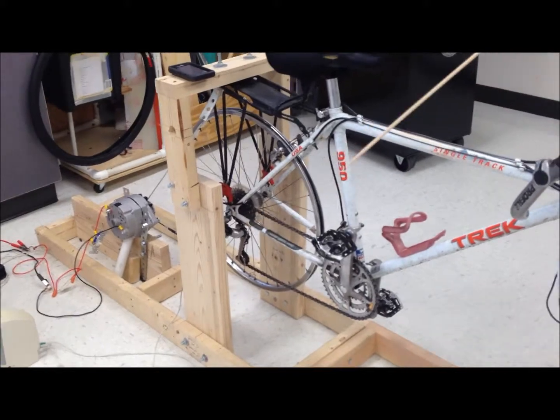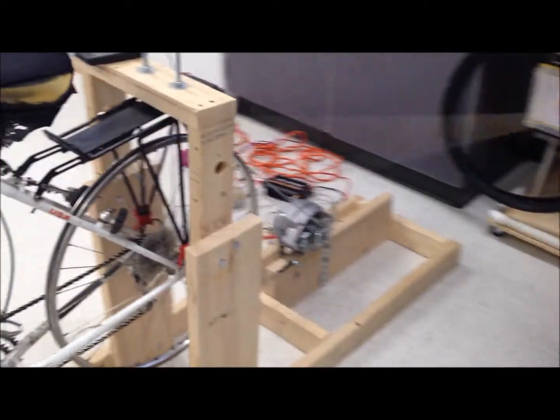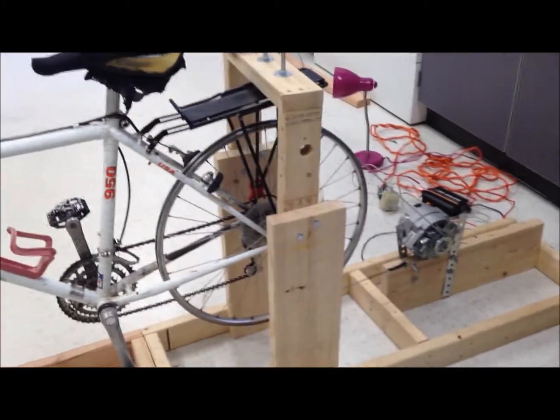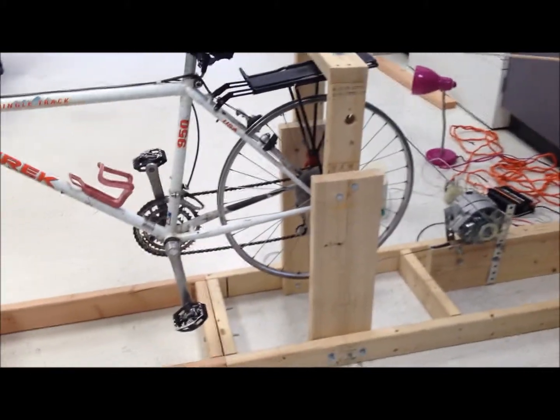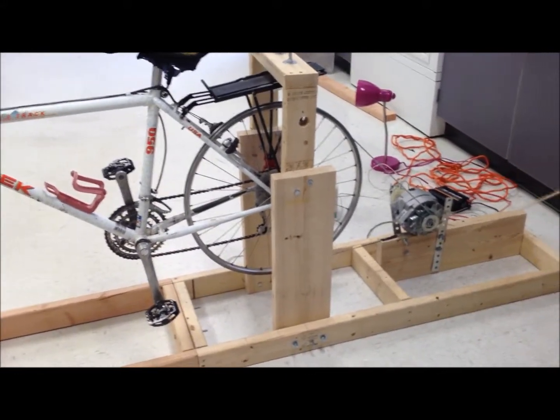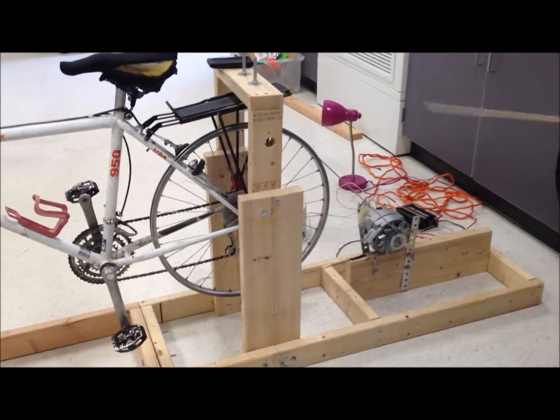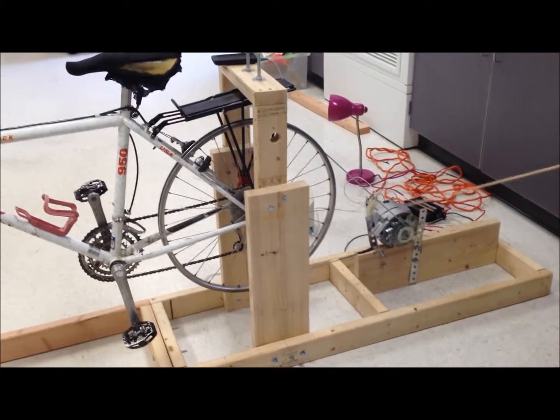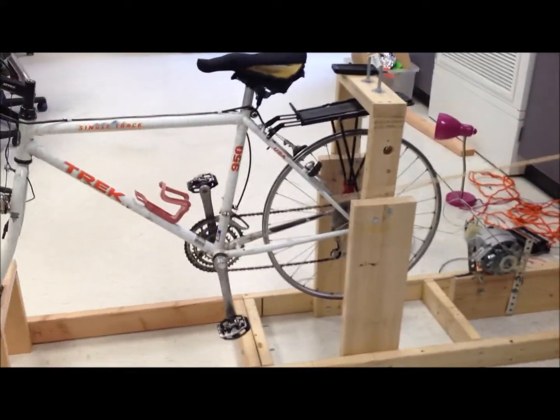The rear sprocket and the rear wheel are permanently attached, and the rear wheel is connected to an alternator by a bungee cord acting as a belt. By pedaling this bike, it would turn the alternator. An alternator must rotate at least 3,000 RPM, and it would be impossible for a single person to attain this, so the mechanical advantage of the bicycle generator is important.